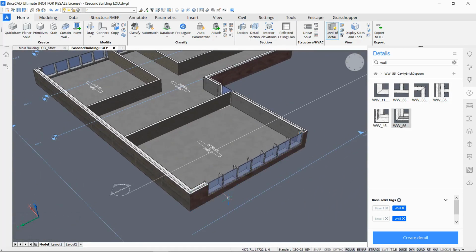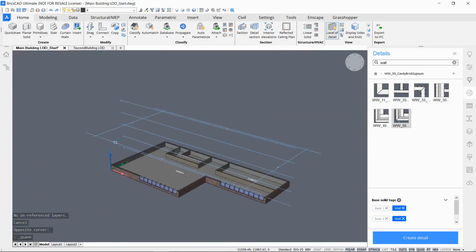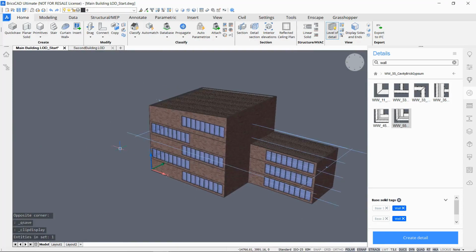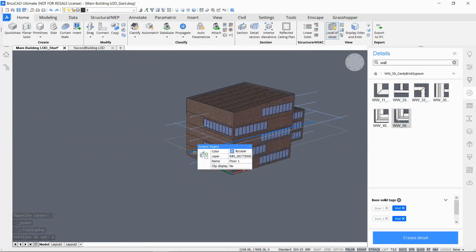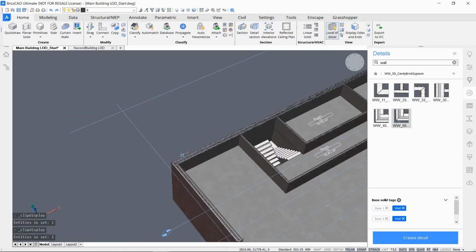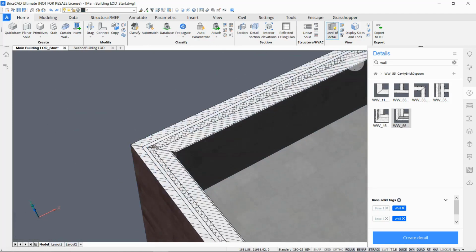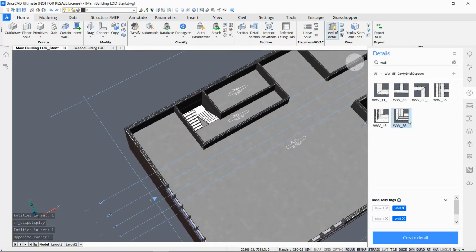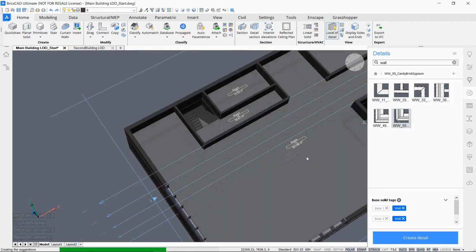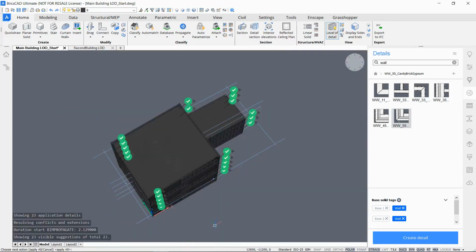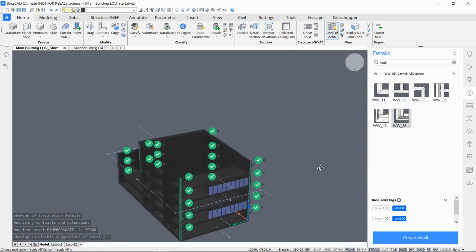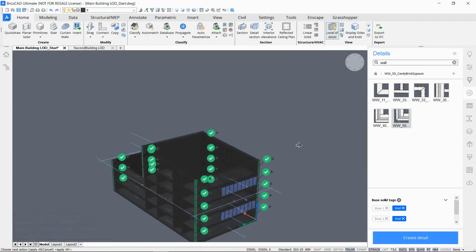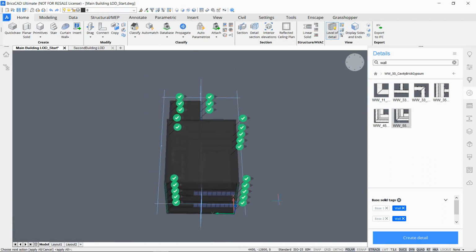We can do the same thing for the other model, which is the main building. If I open up here a floor section, doesn't matter which one, and I zoom in, you can see the connection is also not realistic and not correct. So if I also just drag and drop the same detail into the drawing, it will propagate automatically and give us some suggestions. So here, this is our blind wall, so with the different compositions. So the rest we can unselect like this, enter.